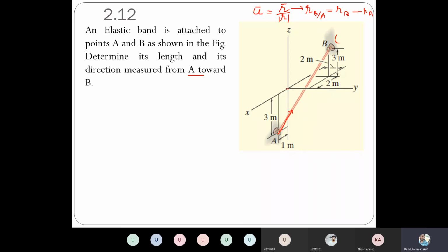If we start from here, we have to move from here to here, in the y direction. How much is that? 3? No, that's 2, because from here to here is the same as from here to here. That's 2 meter. So we move in y direction, and then in the negative x direction from here to here, 2 meter in a negative direction. And similarly in positive z direction from here to here, and then we can reach point B.